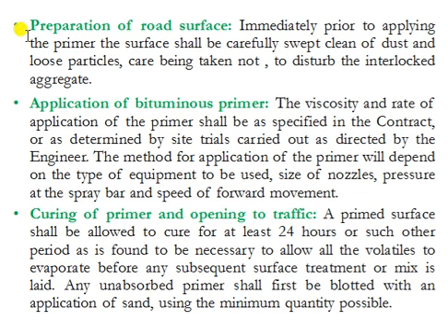So the next stage is preparation of road surface. Immediately prior to applying the primer, the surface shall be carefully swept clean of dust and loose particles, care being taken not to disturb the interlock aggregate.